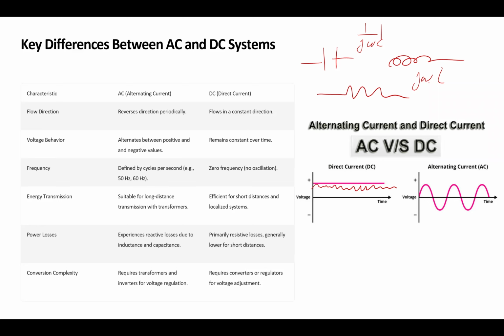Now, how do we compensate that? Remember, if L and C deviate our energy from active power to reactive power, that means our power quality is getting lower. Does that make sense? What did I mention that could be useful to compensate and fix that problem? FACTS devices. They could compensate that difference, so we again have better power quality in our system.